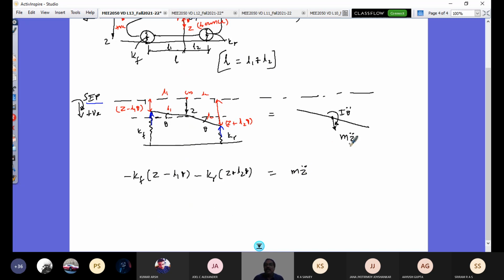So what is my equation? This m is here the sprung mass. So unsprung mass is neglected, not accounted. The reason for not accounting unsprung mass is that the frequencies are well separated, and you can consider the motion of the body independently. The excitation that comes to the body comes because of your unsprung mass, but the unsprung mass has its wheel-hop resonance at 10 hertz, so the amplitude entering the body is very small. So I'm making that an independent entity. I just look at my vehicle body with only the springs of the suspension, not accounting for the unsprung mass and the tire-wheel assembly properties. That is what is to be understood very carefully. That's why it's Kf and Kr alone, which come from the spring stiffness of your suspension.